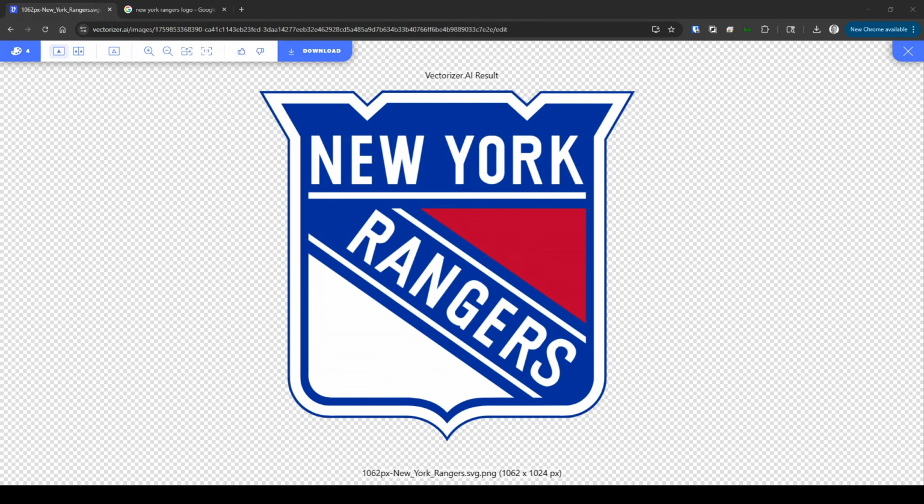So for this one, the main thing that I'm looking at are small pieces and letters. I generally don't want to print a bunch of small pieces and have them inserted. So the thought process here would be to have a white base and then have a blue piece printed here so that you can read the letters. The letters are essentially negative space. So you're not printing these letters as white letters. You're printing this blue piece, which is going to show the white through the blue piece and form the letters.